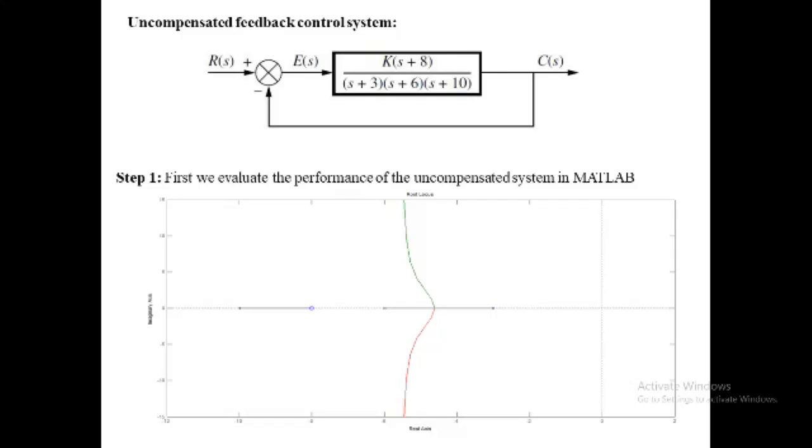Next, determine the gains K1, K2 and K3, as shown in the first figure. Now simulate the system to be sure all requirements have been met, and at last, redesign if the simulation shows that the requirements have not been met.